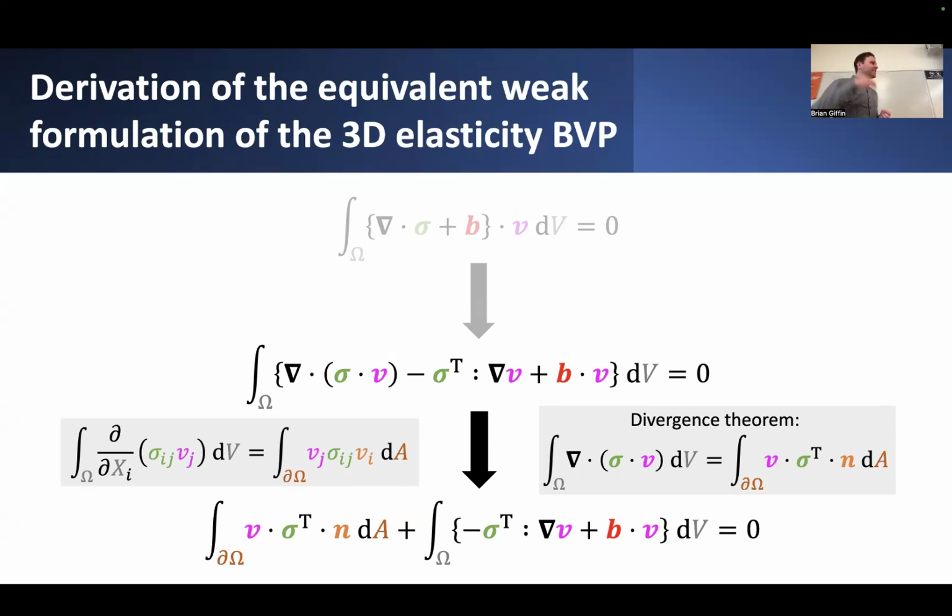So we have applied the divergence theorem, again written here in index notation just for the sake of comparison and to reconcile which components are being multiplied with which other components in these different tensors and vectors appearing in this expression. And pardon me, but I think this expression involving vi should be an ni, the normal to this boundary, so the surface normal aligned with a particular differential surface element.